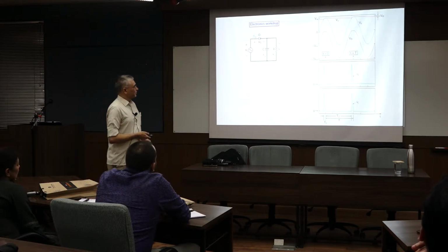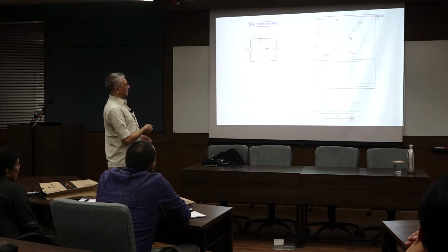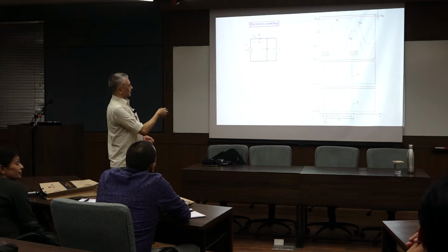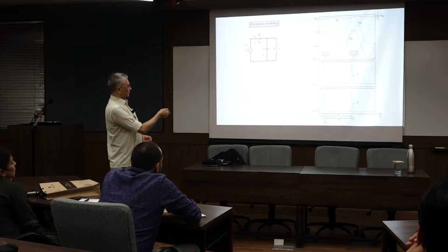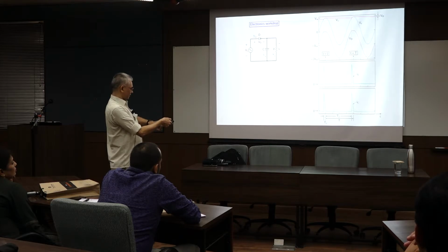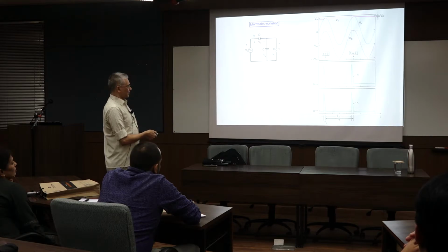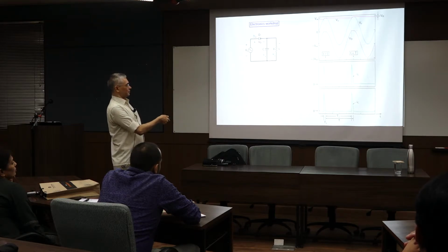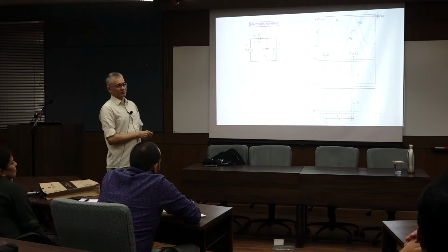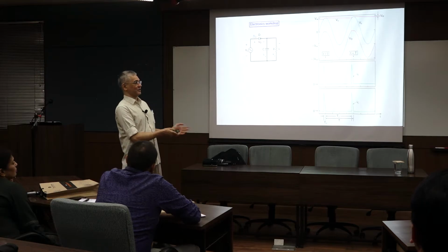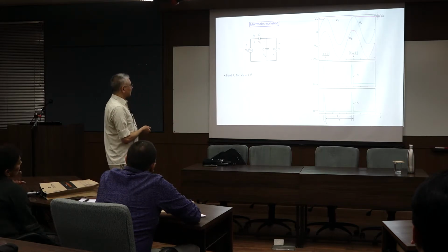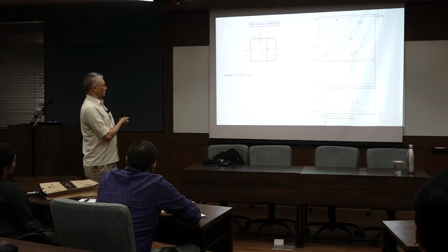Here's another question. It's a half-wave diode rectifier, and this is the input voltage, that is the output voltage, and this is the voltage across the diode. Okay, so there's a reverse voltage here and so on. And these are diode currents. So the diode conducts in this area. Then the rest of the time the current is 0 and so on. And this is the capacitor current. Alright, so now first of all, these plots nobody has seen before, although they are so very important. Nobody has seen these plots, because they are not in the textbook. Tragedy.